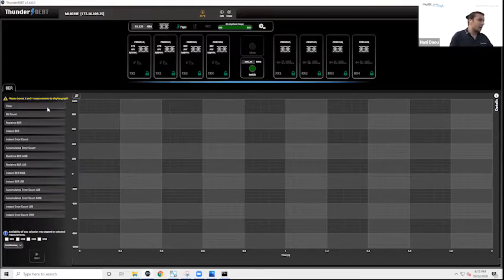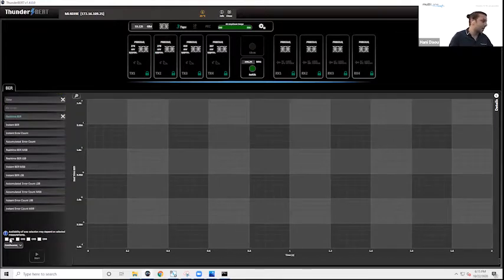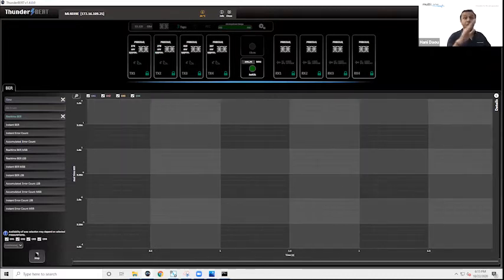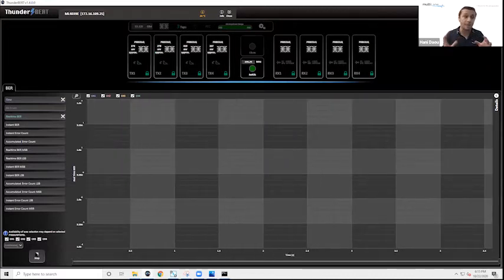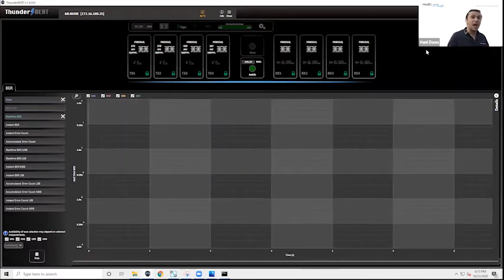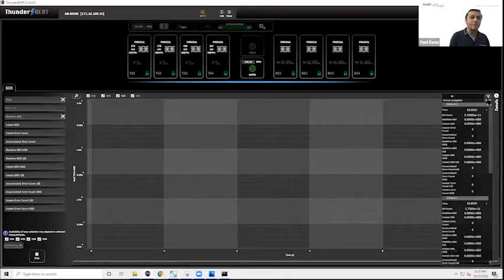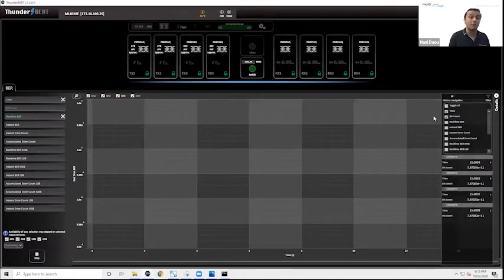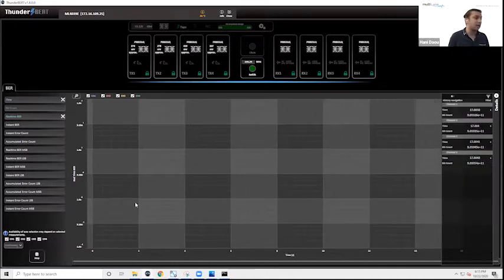Again, what I told you guys is, as I set up a bit error rate test, I configured these transmitters to operate at around, let's say, 1E minus 12 with full blast, putting the taps on the maximum power consumption possible. And as you see, as I take a look at the details tab, we are in fact running error-free on all 4 channels. And that's great.